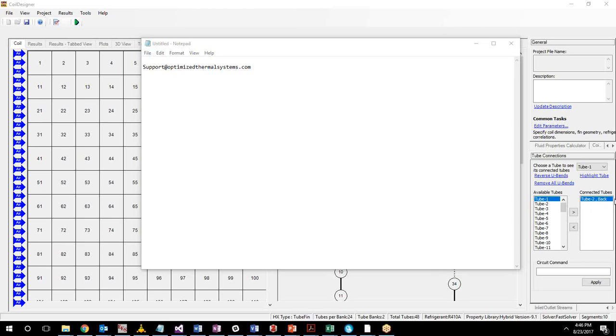And there's a question about tube orientation, if the tubes are not horizontally oriented. It's a good question. In general, we see that the gravity effects in most tube fin heat exchangers of the size range we see in HVAC usually are not extremely influential over the overall performance, and we can get reasonable results whether the tubes are oriented vertically or horizontally. But fundamentally, the question comes down to how the correlations were developed.